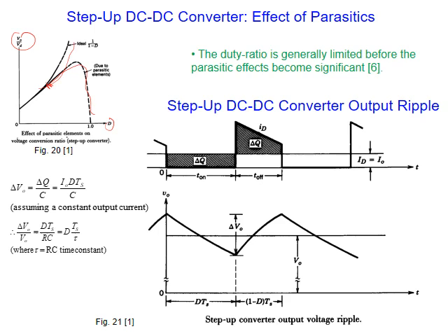Why does it go down? Because when we deal with the capacitor or inductor, we assume that they are pure capacitor or inductor, which is not the reality. In reality, the inductors have their own resistance and capacitance. The same thing for the capacitor, its own resistance and inductance. Plus, in the circuit there are stray inductances and stray capacitances. For that, we have to consider this.